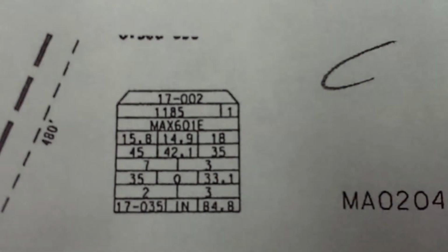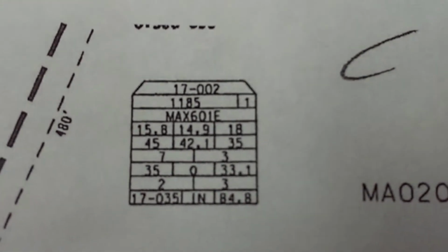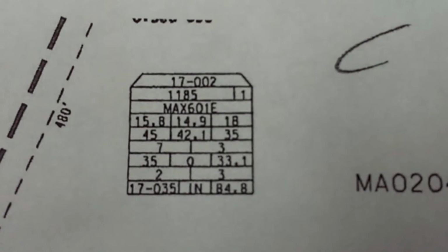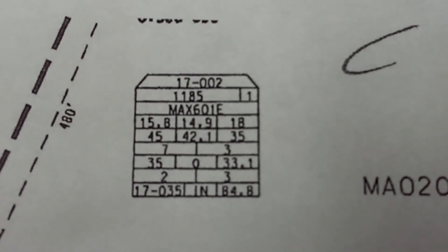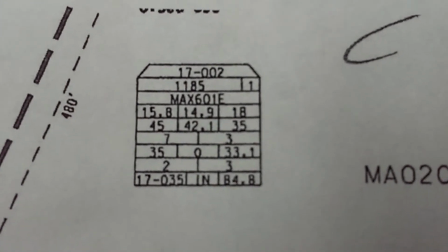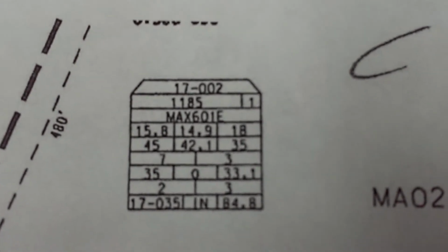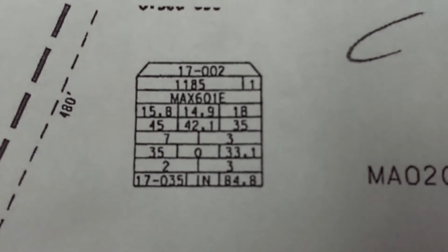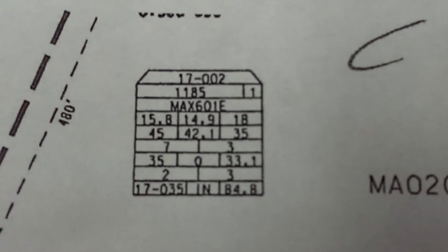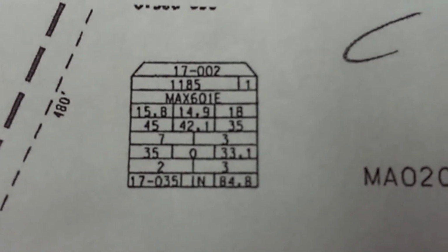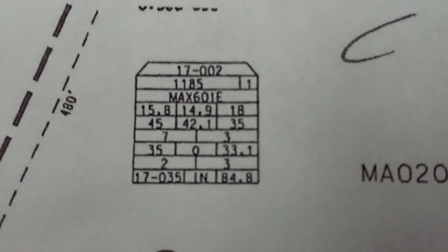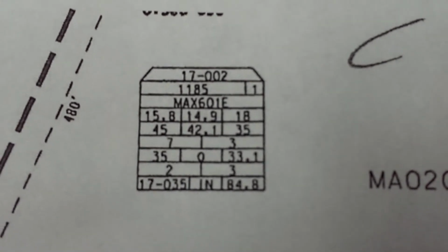Good, important information. Why is that important to me? Well, there's electricity in our system, and if I know I'm amp number 1, and I know there's an amp 2, 3, 4, what does that tell me about this amp? It's got power in it. If I pull the fuse on it, who did I just shut off? Everybody, the entire node. So please don't do that without somebody knowing.